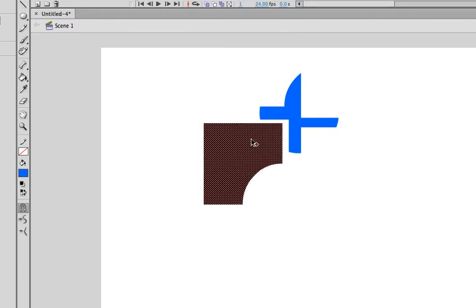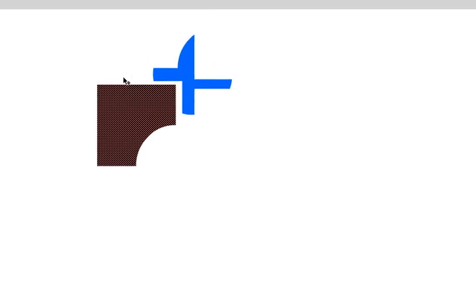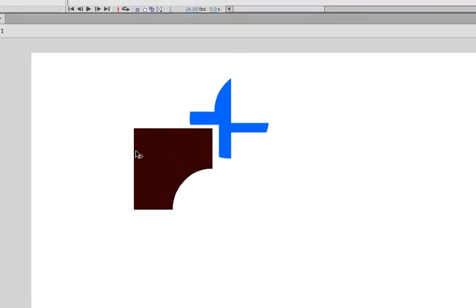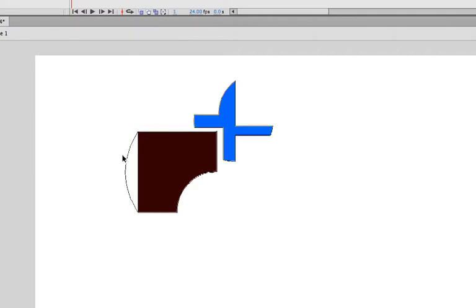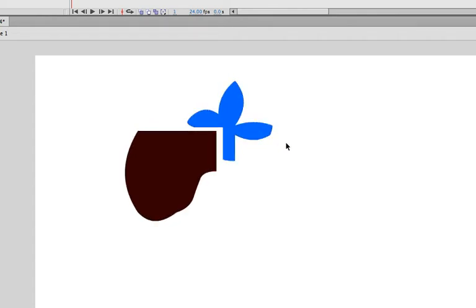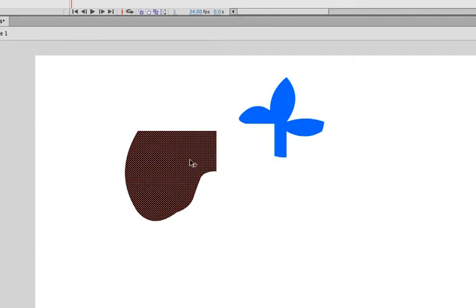One other thing about shapes drawn in merge mode is if you hover over the edge of a shape, you can actually click and drag the edge of that shape out pretty easily. So you can add some interesting things with that as well. You can select the object by clicking on the fill, moving it. But notice if you hover over the edge after it's selected, you can only move it. You no longer get that icon with the bend.